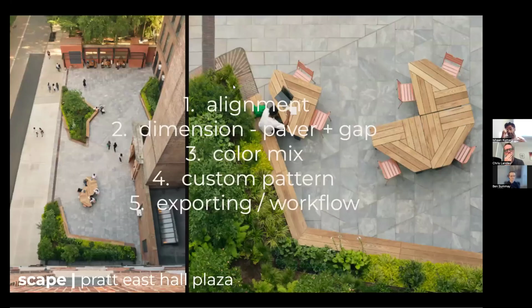And so I know that the paving workflow is magical because you could iterate quickly, change the size of the paver, change the size of the gap. Oh yeah. I mean, you're looking at a much, much easier approach here for paving, where you set those dimensions of the paver that you're working with, you set the size of that gap, you define the boundaries, each of these individual boundaries that you have here, and the magic kind of happens. And you have the pavers being trimmed to that edge automatically for you.